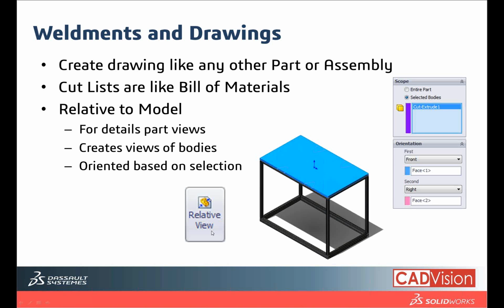It doesn't come out. Okay, always use the command search options in your SolidWorks, which is a very useful tool. Just click on the relative views and look for this icon. Once you click on this and zoom, it will bring you to the parts level, and then zoom into that part.